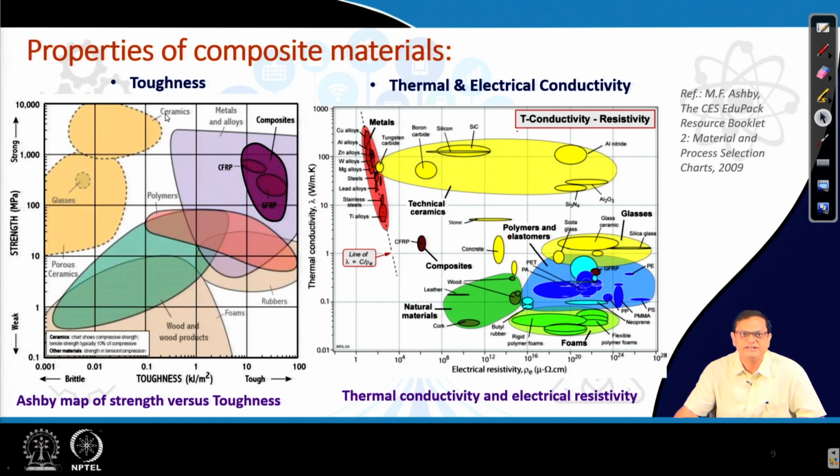So, toughness is required, as we all understand, and we can again see that ceramic materials and glassy structures all have very good strength. Okay. However, their toughness is very poor. As I was mentioning earlier, they fail catastrophically, they show brittle behavior. And how do you overcome that? Again, you make composite materials of those particular materials, keeping them as matrix, and then try to improve their toughness.